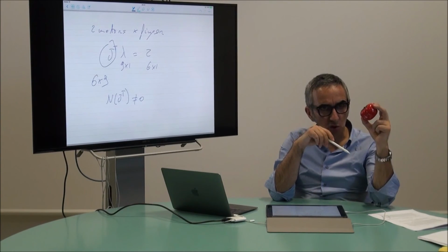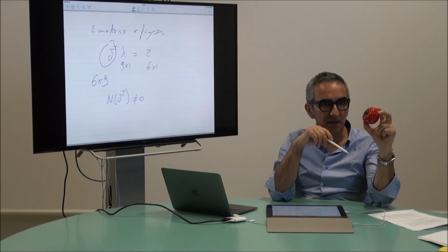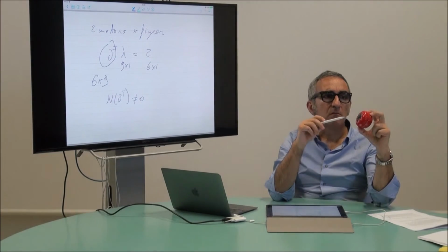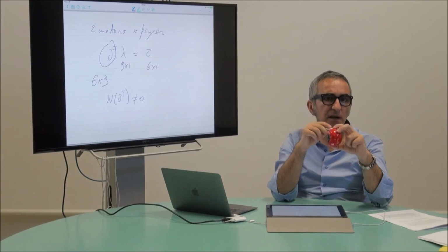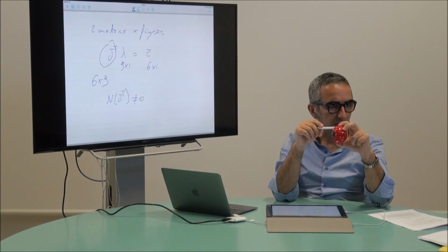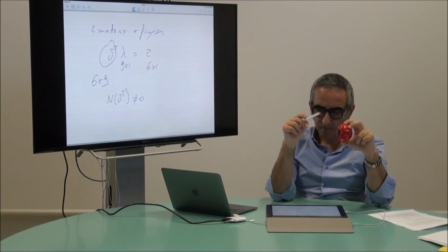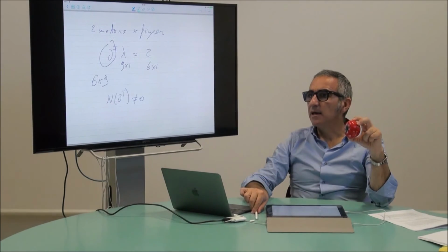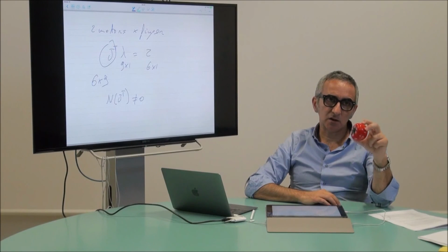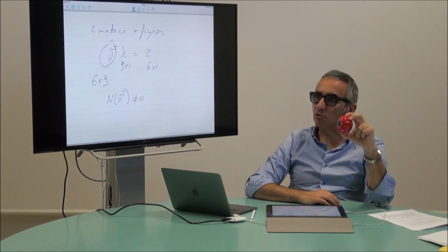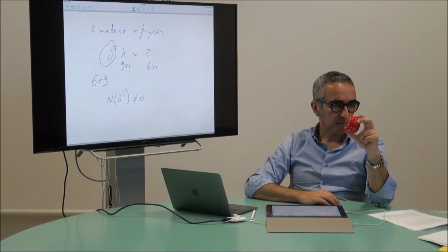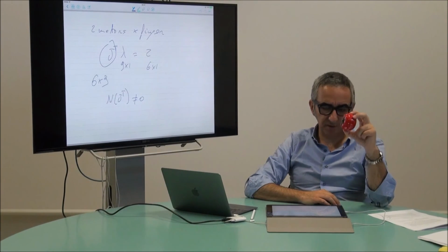Because when we control an object like this in the fingertip, for any lambda we want, that our brain selects, there is enough control to do it. Clear? Okay? And this is also the reason why the first hand of Salisbury has been designed with 3 motors per finger, 3 independent motors per finger.